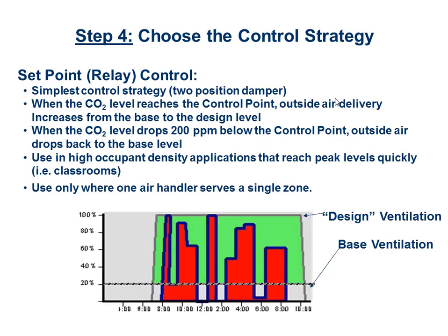All right, the different ways we can control these sequences. The most simple way is what we used to do 10, 12, 15 years ago, which was just set point control. I have my ventilation rate coming in, which is the top bar going across here at the 100% line. If my CO2 level drops below my set point, say from 1,000 parts per million down to 800, I would say, okay, I'm overventilating. Let's put the damper at its lower position that just takes care of VOCs and not the people. Boom, drop it down here.